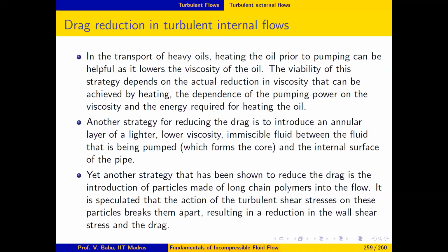And since this is the fluid that is in contact with the wall, the skin friction drag in the viscous sublayer, which is proportional to mu times partial u partial y, will be less, although du/dy is the same. Mu times du/dy is less because mu is less on account of the fact that the lower viscosity fluid is in contact with the wall.